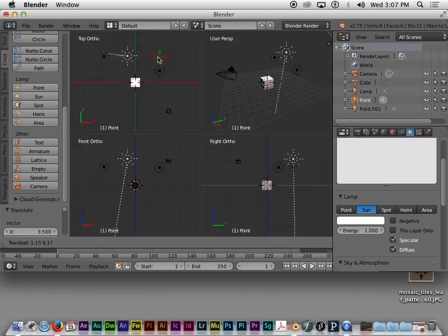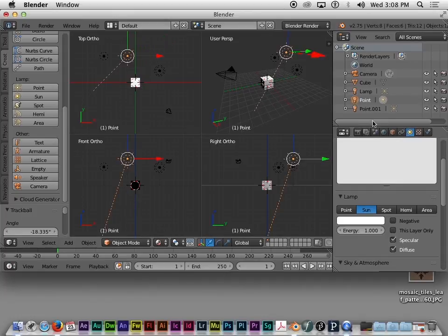So it's fun to work with if you need a harsh directional source. I recommend working from the top view and using the flexibility of the full rotate feature by hitting R twice, so it shows a red and green arrow set. And then you can move it around and push it in any direction that you want it to aim in. All right, so that's the sun.